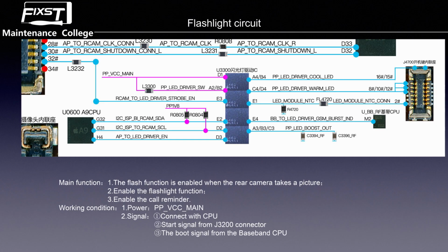These three pins are the booster system. As you can see, in this line there are two capacitors. These two capacitors are booster capacitors. These two capacitors cannot be missing, cannot be damaged, cannot be loose. If we have some problem, we can only change them with the same one to install it.